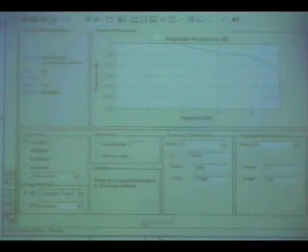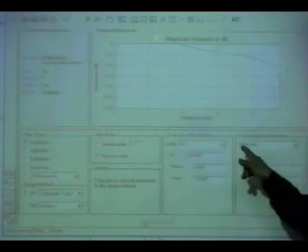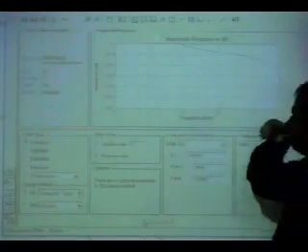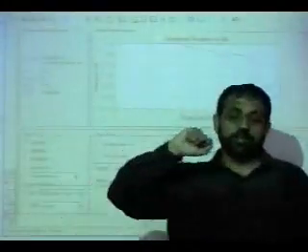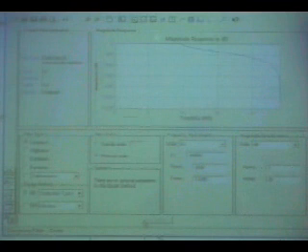So MATLAB comes back and tells you that a type 1 filter can be designed using only order 13, meaning only 13 poles. Compared with 31 poles for the same specifications, it's a significant reduction in complexity, only 13 poles.